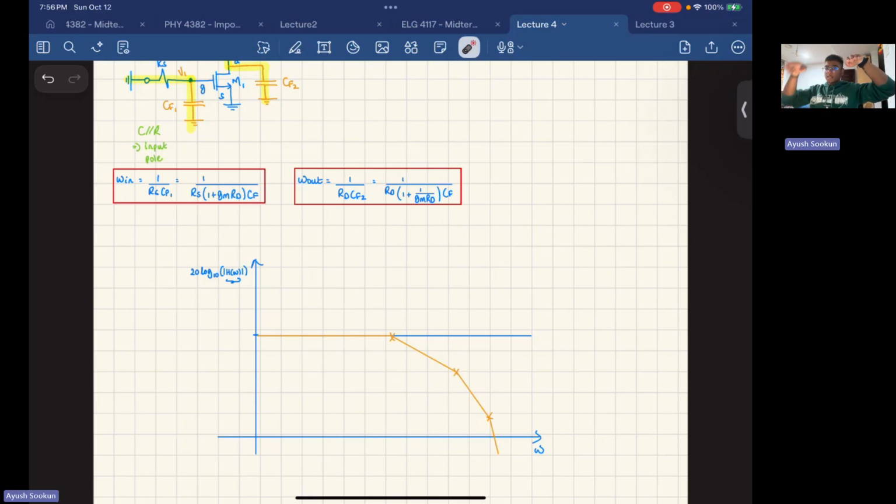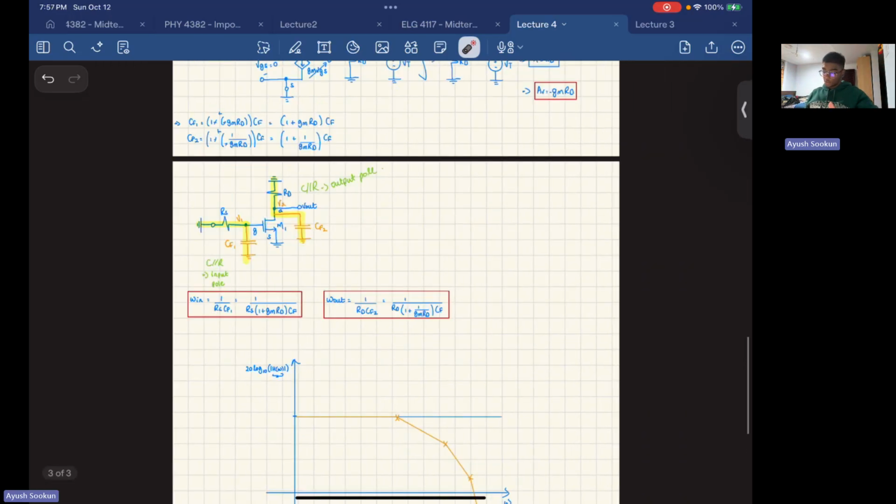You're going to notice that your circuit works as an amplifier only between two different points. At some point, you're not going to have any gain because you're going below zero, your gain attenuates to zero. There are only two points, a range between which your gain is steady, and that's what you want. You want to maximize that bandwidth. So this is the intuition.